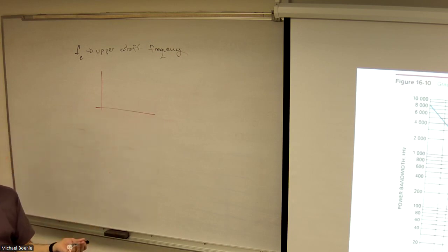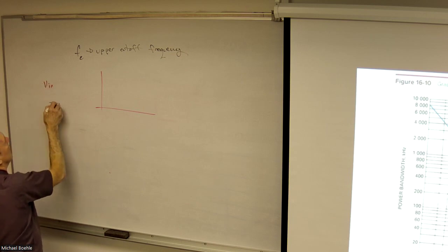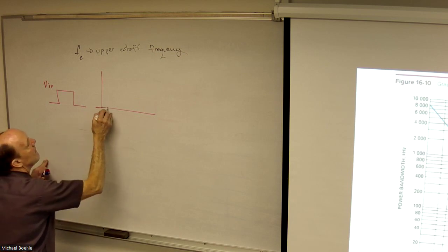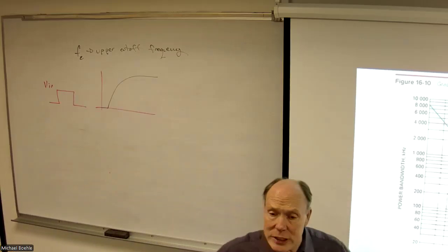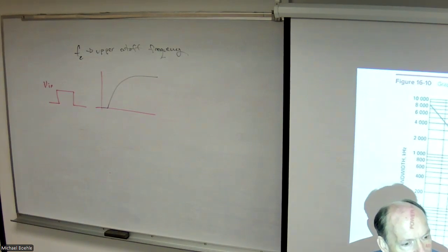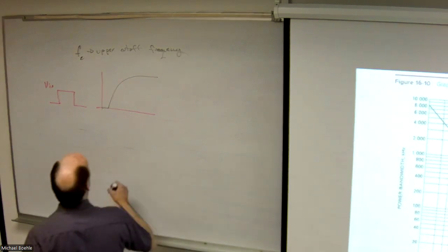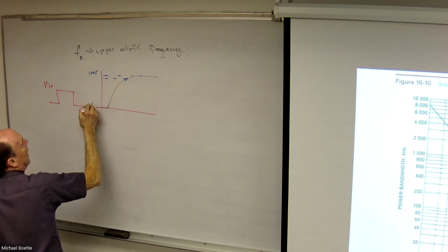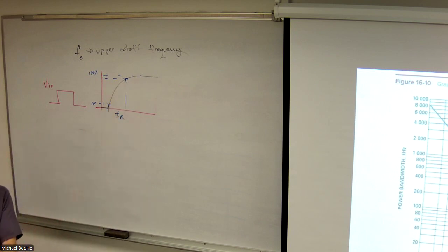You put in a square wave to an amplifier that has an upper cutoff frequency, what happens? It's like a charging capacitor. It's essentially what you have. And of course, when you found your upper cutoff frequency, you're like, oh yeah, well, there's 100%. So we'll find 90, we'll find 10, and that's your rise time. Okay? That's what happens if I put a square wave in.